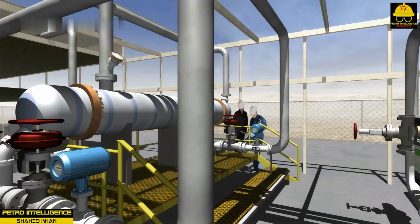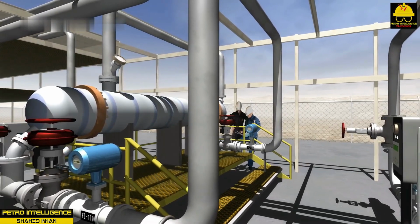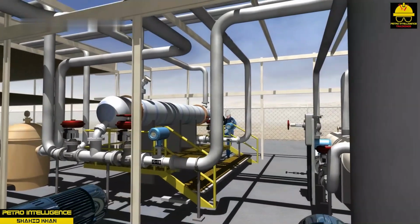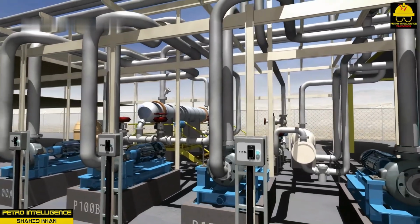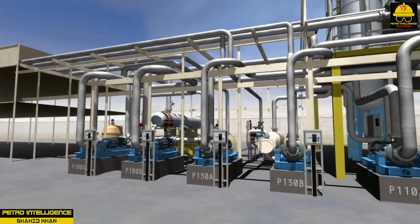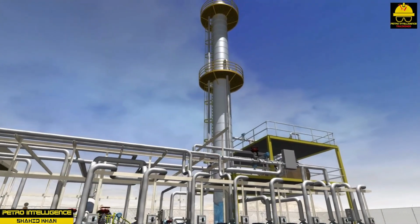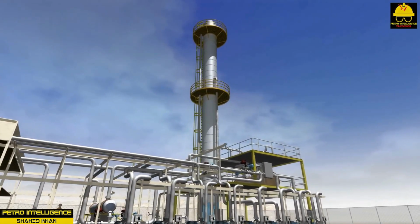Distillation separates the basic components or fractions of a mixture by their individual boiling points. During the distillation process, a mixture is heated until it vaporizes, then is recondensed on the trays or at various stages of the column, where it is drawn off and collected in a variety of overhead, side stream, and bottom receivers. The condensed liquid is referred to as the distillate. The liquid that does not vaporize in a column is called the residue. A distillation tower can be compared to a series of stills placed one on top of the other. As vaporization occurs, the lighter components of the mixture move up the tower and are distributed on the various trays.